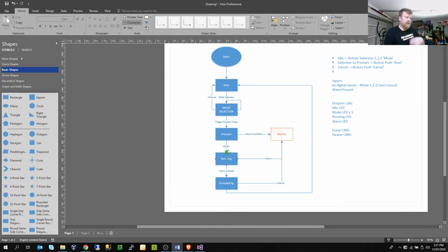Typically what I would suggest is the logical flow for a normal program is to do something like read some information, make some decisions, add those numbers up, subtract them, work out if they're within range, scale them, things like that. And then once you've worked out the information that you read in, completed your mathematical or logical process to determine what's going on or what needs to happen, then drive some outputs to make that happen. So I would separate my program, on a small process like this, into subroutines, and I would have one for reading field I/O, input-output, maybe a separate one for scaling.